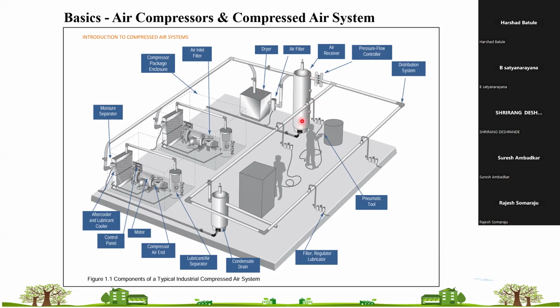If the air receiver was in place, you need to drain that air receiver first. You can drain from this particular condensate pipe, or there are additional discharge points given on many receivers that we can drain from. Ideally you need to empty the receiver, so all water and all air will be thrown out of the receiver. Only this piping network and the receiver are in place.